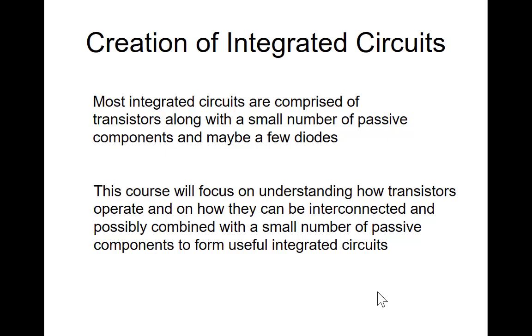I've got a wafer I'm going to pass around right now. And my request is that you use your eyes but not your fingers to look at it. This is an 8-inch wafer. It's a prototype structure. And what you'll notice is there's a repeated pattern on here. Each one of those repeated patterns is what would be called a die if this were broken apart. So this die is pretty big. The die are about a square inch on this wafer.